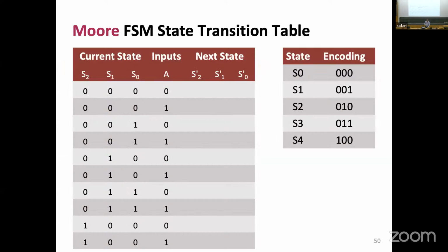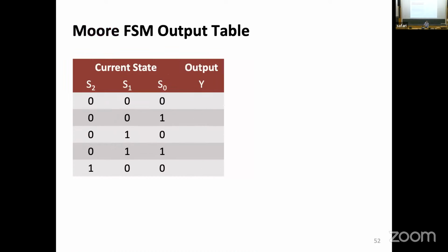Okay, so now let's take, I'm not going to do this, but it's the same type of thing. You have 3 states now, and you have your input, and you can calculate your next states. In this case, notice that I had a lot more freedom to choose the states. I only have 5 states, but I use at least 3 bits. So this means that there are three, how shall I say, parasitic states there. Who knows what happens when the state is 111 or 110? Those are all possible things. They can be expressed, but they are not valid. I can fill my things.